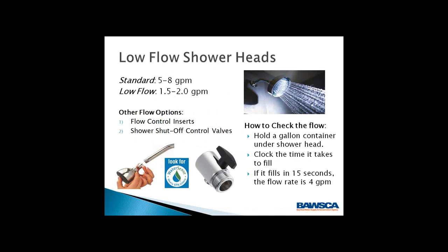So talk a little bit about low flow shower heads. Your standard shower head gives about 5 to 8 gallons per minute. Low flow is about 1.5 to 2 gallons per minute, so it's large savings right there. Main question I always get asked is, so if I get a low flow shower head, does it affect the comfort level of my shower? And nowadays with manufacturers taking this into account, I can guarantee you that low flow shower heads can be just as comfortable, and they take in different statistics in terms of how to deliver larger droplet size, even though it's low flow.